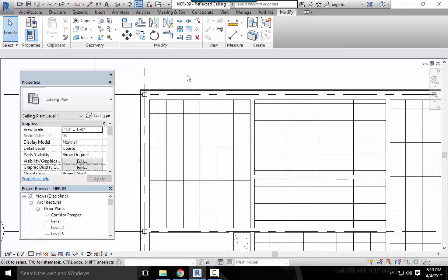On to the next task here in Chapter 9. Setting ceiling element properties. As I mentioned earlier, ceilings are set up in a fashion similar to floors. So it stands to reason that you'll see many similar properties. Before you get started, let's make some modifications to the west wing. The object of this procedure is to add a hard ceiling with metal framing, gypsum, and a 3/4 inch cherry finish. To do so, however, you need to modify some of the walls.